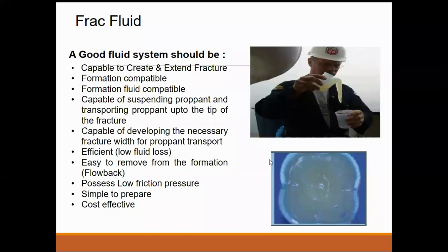So the fluid should be as clean as possible, and it should not be producing any fines or any residue in the formation, so that when you recover the fluid, the channels that you have created while fracturing remain open. It should possess low friction pressure. Okay, so now the friction pressure: if any fluid is giving high friction, it will affect your pumps, because more pressure would be required to pump the fluid if the friction is very high. So it should have low friction properties. It should be simple to prepare, and definitely cost is going to be high.